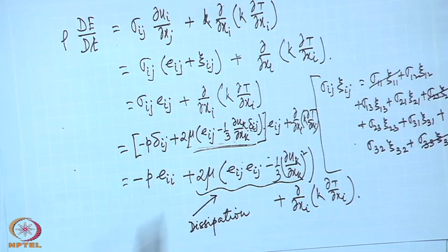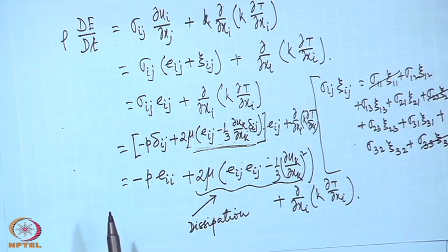The first term is the conventional, familiar pressure-volume work, PV work, called compression work, and in this case this is a useful work. Whatever work we give, we can get it back. Whatever work we use while compressing, we can get back during expansion.